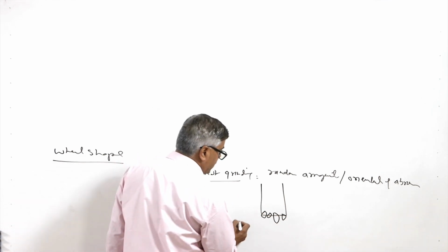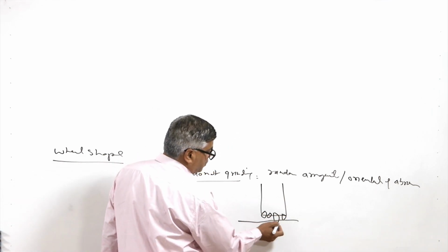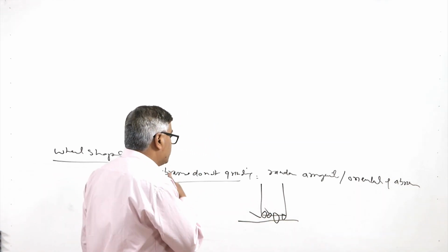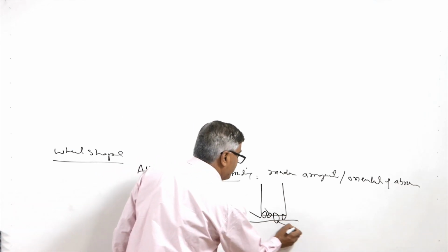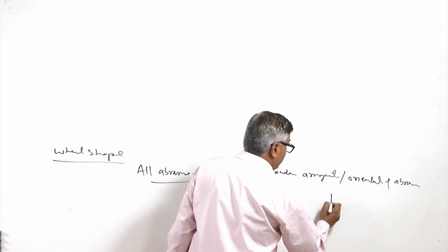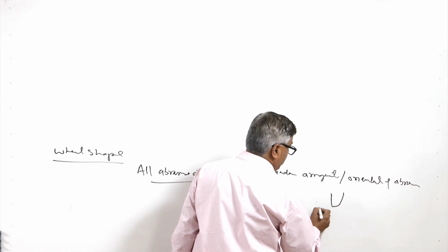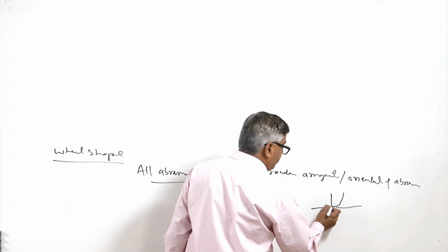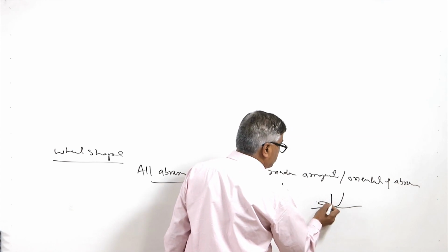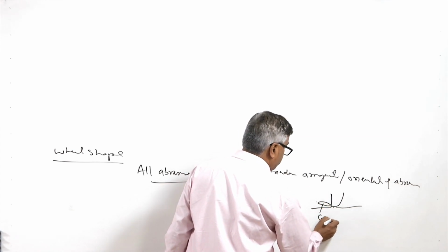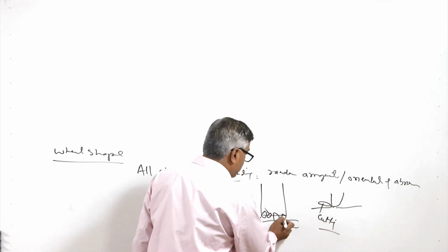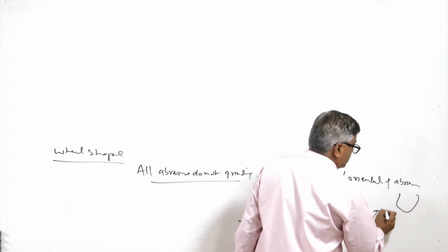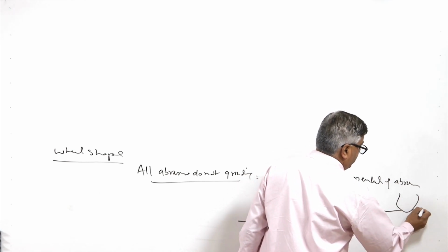So, if we see this scenario, maybe 2 abrasives will be performing cutting, and these 2 will not be performing cutting. So how will the cut be performed? The abrasives will get inside the workpiece, and it will be forming the chip in this form. So, cutting is being performed in this case. For the second case, here the abrasive is just penetrating but not cutting.